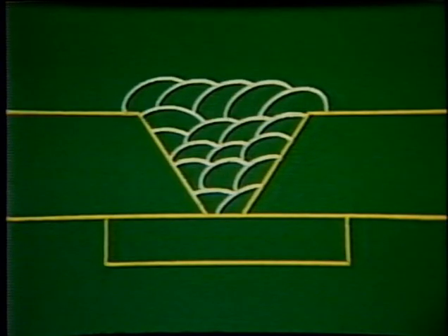Incorrect work and travel angles may improperly direct the filler metal and may also cause the weld deposit to pile up and droop. Another example of improper technique is the improper sequencing of weld beads. By locating beads improperly within layers or depositing too many layers in a joint, the face may become excessively reinforced or inconsistent.